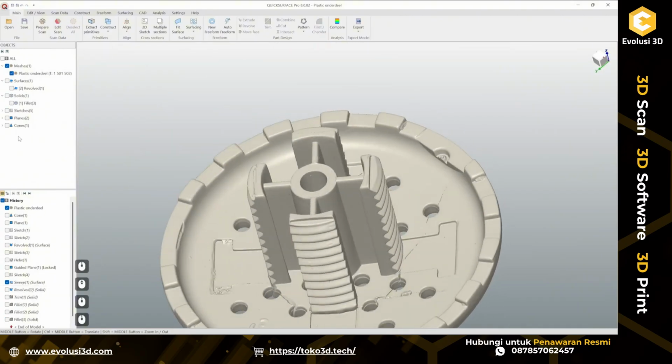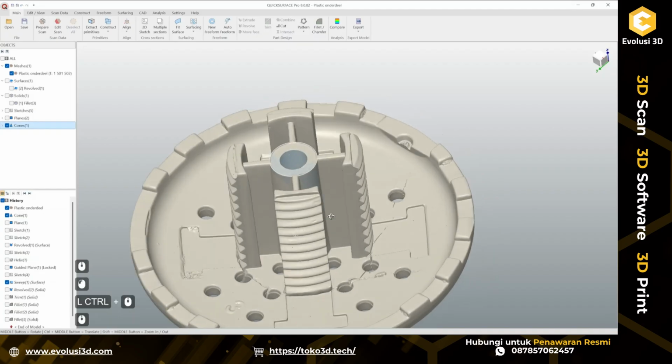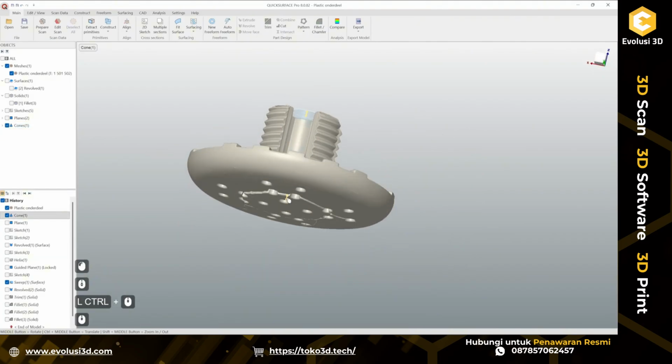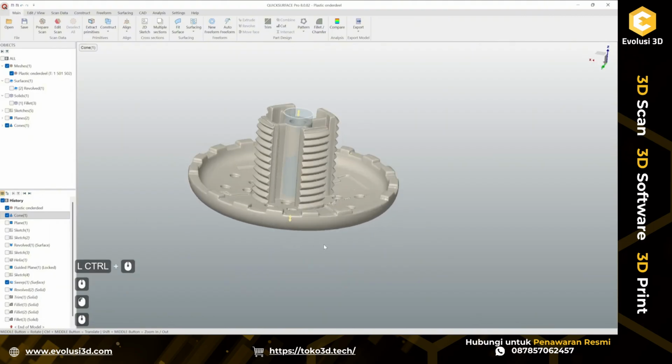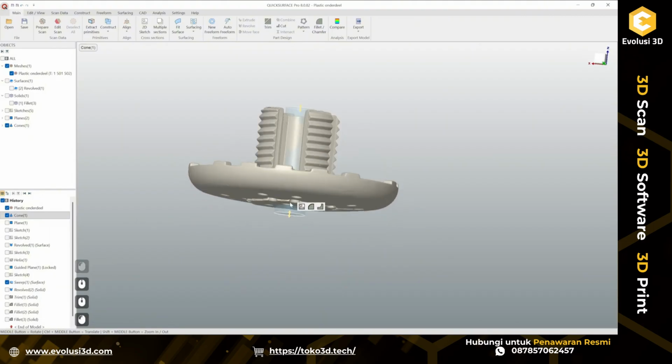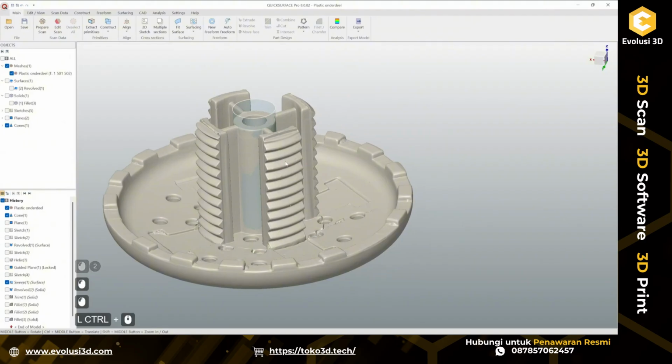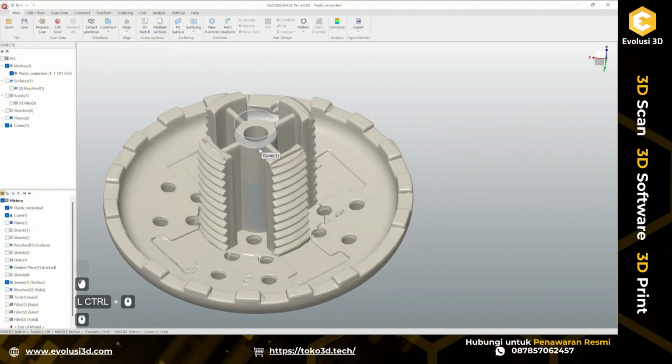And in order to do that, I have this cone that I previously fitted to scan data for aligning purposes, like this. So actually I'm going to edit this and say I don't need this to be a solid but a surface. Okay, so I have one feature.